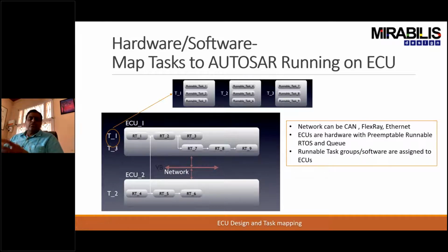What we're trying to do is get all the sensors connected across the network, connected to this ECU, and we're looking at what's going to be the response time from this ECU. So in terms of when the task is ready, the time it takes to go to ready to run, and then of course actually executing of the data. So is there a huge difference in the latency between ready to run and actually executing?